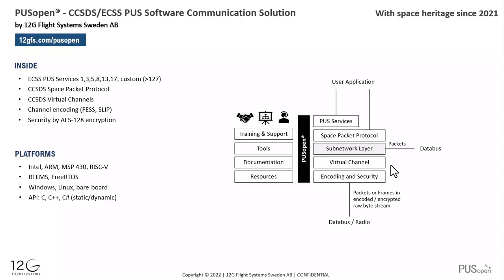So let's say pipe 0 might be used for highest priority messages like alerts when the batteries in a satellite are running low, and when you want to prioritize that message even in the middle of downlink of, let's say, imaging data, you can use that pipe. You can put the message there, and it will be basically prioritized. It will be downlinked in the byte stream here, even in the middle of the image downlink, and then on the ground you can again get that message separated from the image downlink,